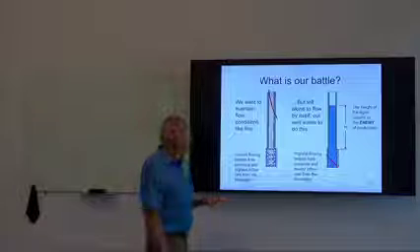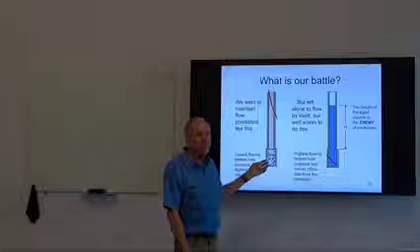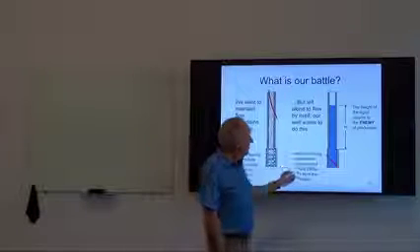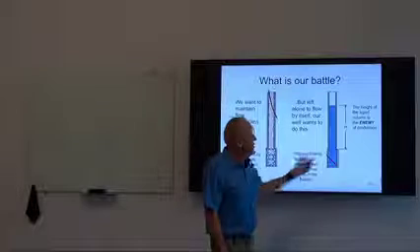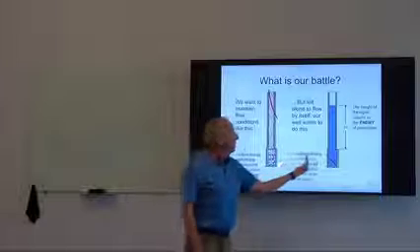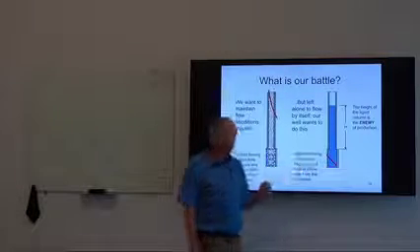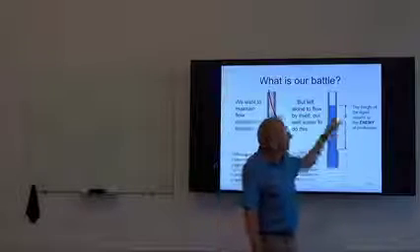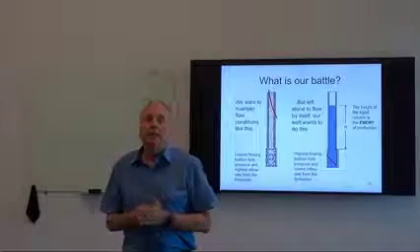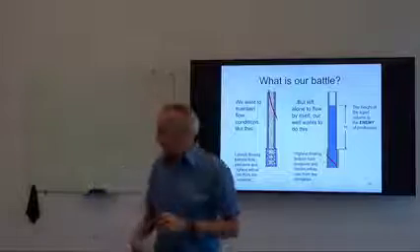basically kill the well. Here we have a relatively low flowing bottom hole pressure and highest inflow from the formation. In this case, we've increased the bottom hole pressure and we have the lowest inflow from the formation. Obviously, we would really like to be closer to this end of the spectrum than the opposite end of the spectrum. And if we really want to understand what is causing the problem, it's the height of the liquid column. That is truly the enemy of production.